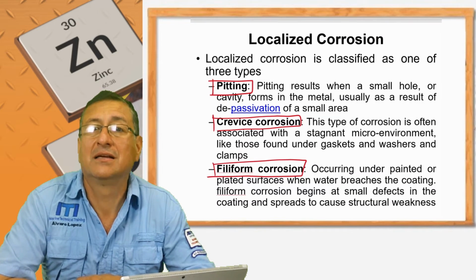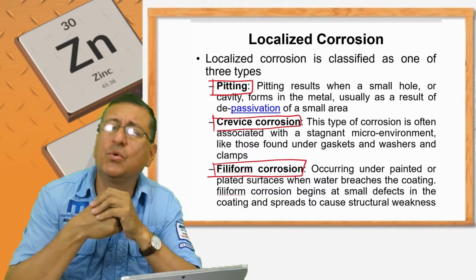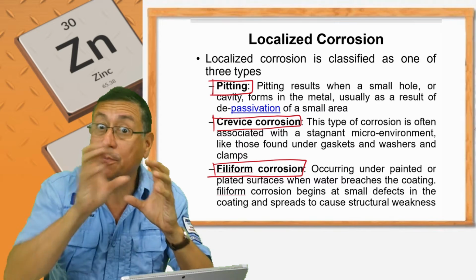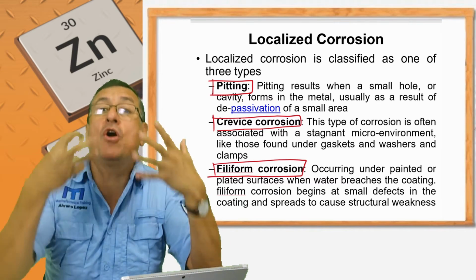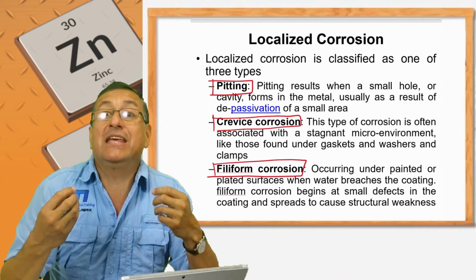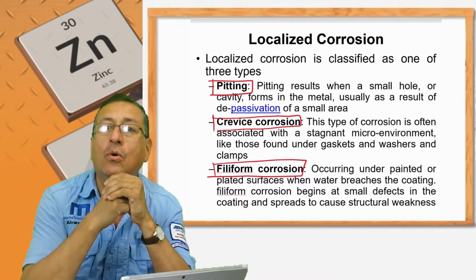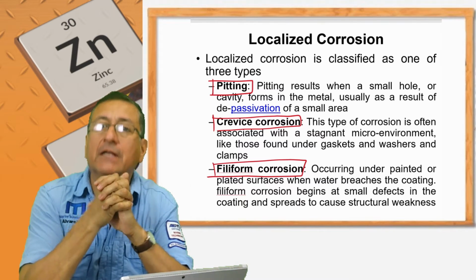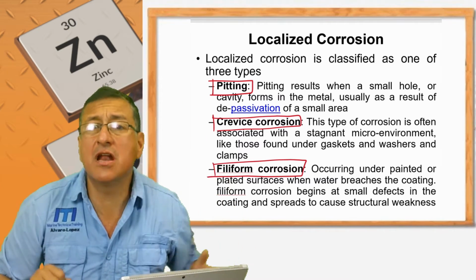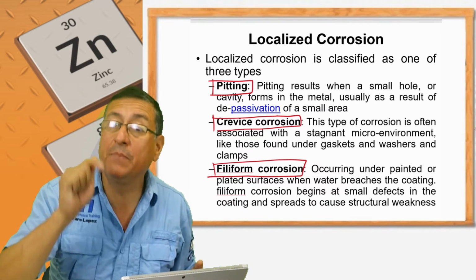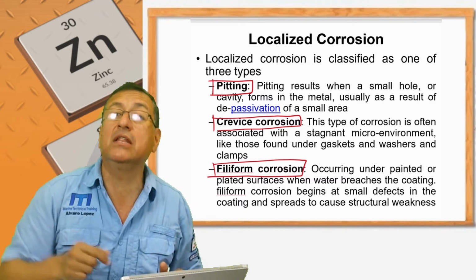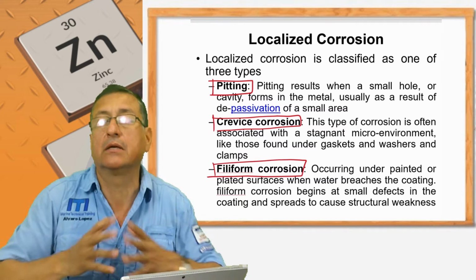Now you understand why marine equipment is costlier? It's because of the quality of the materials. It's because the quality of the paint is appropriate. It's because the motors are ignition protected. And additionally, the copper in the winding is a special copper. For that reason, when you need to rewire the back end of a generator, you need to go to a special place with knowledge of the marine environment, because the wire used in the new winding should be marine grade.